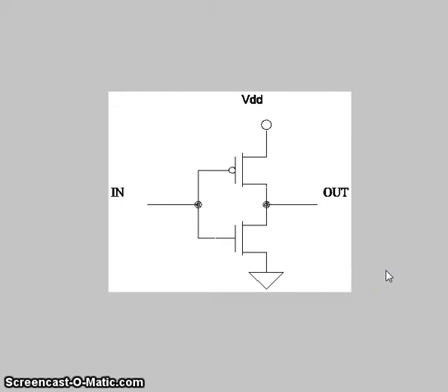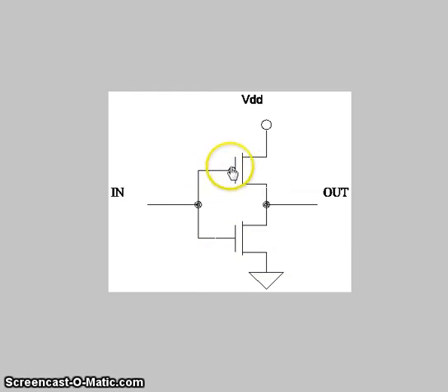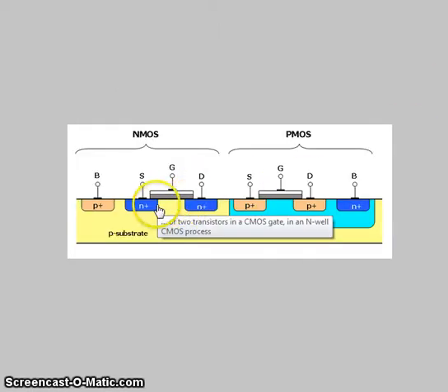So here we have a schematic view of what's inside of our integrated circuit. You'll see that our two gates are connected together, and you'll notice that the P device is denoted by a circle on its gate, and the N device, no circle. You'll notice that there's a separation between the gate and this channel, and the channel is this area right here.